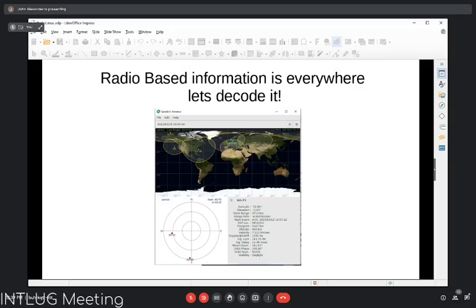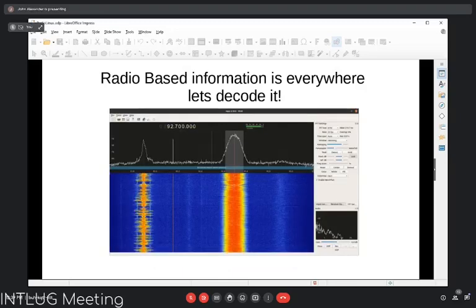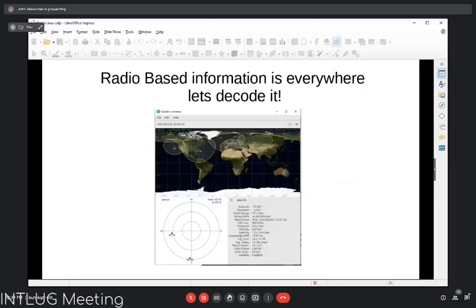But anyway, this will also control your radio. So it will control that, for example, and tune it. And as things are moving, because of the Doppler shift, this will keep your radio tuned up, and it'll also point your antenna. So it'll both point the antenna and tune the radio, and it'll queue up the next, I think it's 7 passes or whatever you've got there.